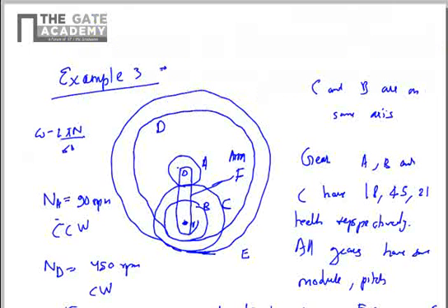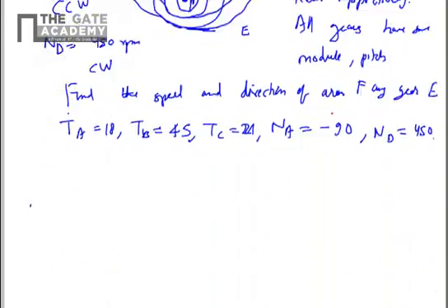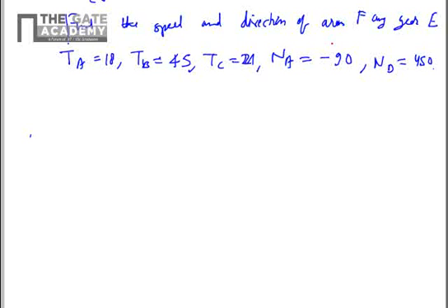For solving this problem, if you keep the arm fixed, then the problem becomes pretty much straightforward. This becomes like any other compound gear train. A is driving C, and C and B are on the same axis. B is driving D. So you can treat A as the input and D as the output. And E has its own angular velocity depending on the angular velocity of C, but it is not connected to any of the other elements. So A becomes the input and D is the output, and it becomes a simple compound chain. We'll determine the gear ratio for that case first.